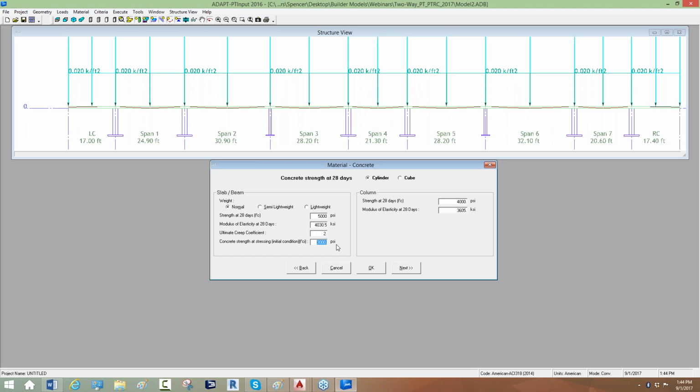For purposes of deflection, in the program, we apply a creep factor as a multiplier to the sustained load in terms of getting the total long-term deflections in the software. So again, this is a simplification. This is non-time dependent analysis, so we can't explicitly capture the effects of creep and shrinkage and time dependent effects over different time steps in the software. We have a program that actually does that for frames called ADAPT-ABI, but this is, again, just a simplified version.